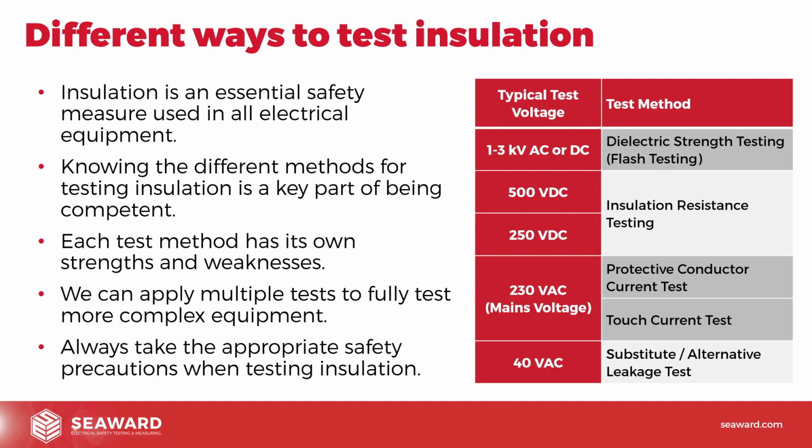If you go back in the day for PAT testing, it was all flash testing, 500 volts testing, because all we were testing was kettles, drills, toasters, things like that that would take it. But now the modern workplace has got way more electronic equipment in there, and we've had to adapt our test methodologies a little bit.